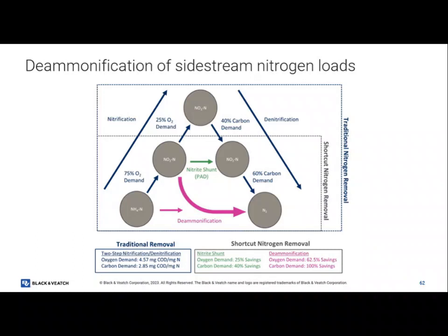But here, if you were to try to say, I'm going to use SRT to distinguish between those, you're trying to control an SRT of 6.2 days versus 6.3 days. Anybody do that? Most of us can't control between 6 and 7 days. So trying to control a decimal is impossible. Even controlling 5 days sometimes is difficult. So you're not controlling to a decimal. But out here, you're talking about having like plus 1 day difference in growth rates.